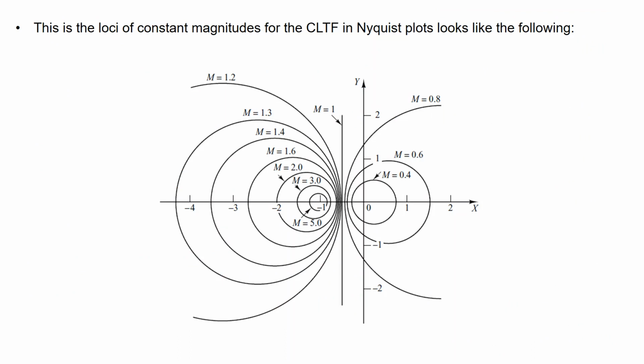When you do Nyquist plot, the curve, the graph of the Nyquist, especially the magnitude of it, since it's indirectly shown in a Nyquist plot, you know, Nyquist plot is a polar plot. So instead of magnitude of the complex number and phase of the complex number, what you have is the real part and the imaginary part.